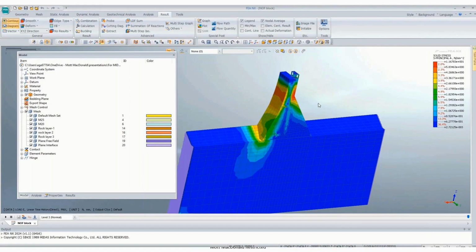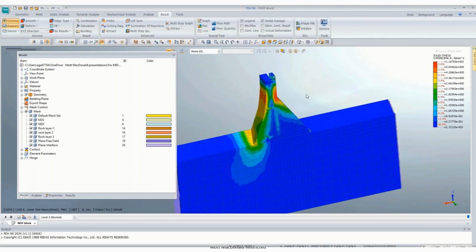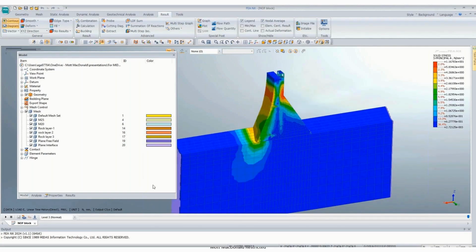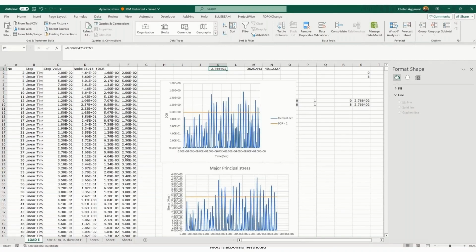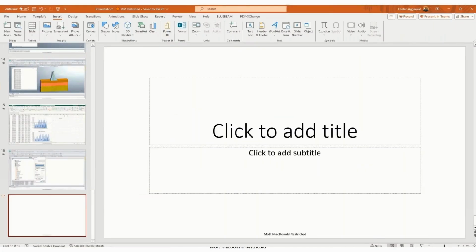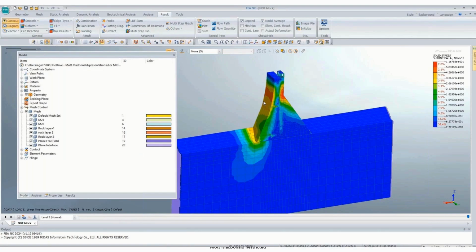dynamic, this ground motion time history. But still I doubt whether the provided time history corresponds to the seismic coefficient of 0.12, because normally it doesn't happen. If the dam is fine for static conditions, most of the time it is okay, and for sliding check and the stress check. So this is it for the NOF block.